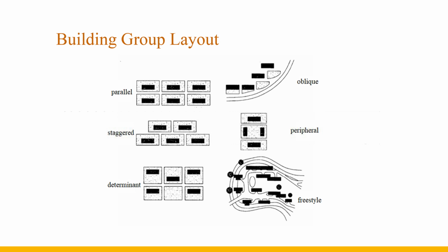Setting the opening in the center is beneficial to the uniform distribution of airflow, and arranging it on one side or setting it on the side wall will easily lead to eddy currents in the room, decrease of wind speed, or even local no wind. The vertical arrangement is also the same. The opening height is closely related to the airflow route.